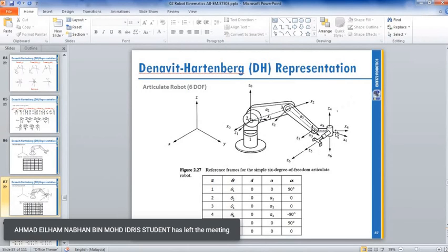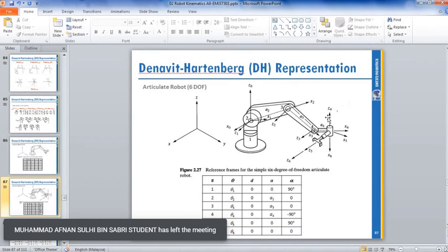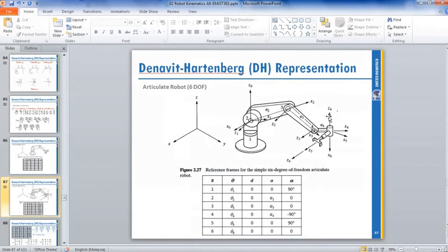And from Z4 to Z5, now you have another change on the X axis. It's not a rotation, it's your mechanical design of the robotic arm going from vertical Z to horizontal Z. So that means you have 90 degrees, because from vertical to horizontal here is counterclockwise, it's positive 90 degrees. And then number 6, you don't have any distance, but you have only theta rotation. You have a motor rotation.